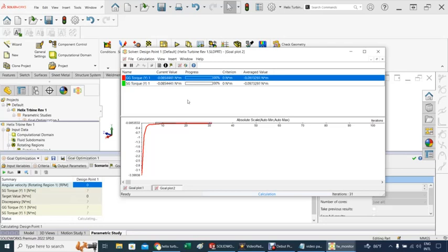Remember, we are doing this now totally automated because basically we know that at 0 we got maximum torque, which is a negative value. Then as we allow the spinner or the turbine to rotate at maximum speed, then we have to apply torque, and that's a positive value. So between the positive and the negative, we know that there's a sweet spot in which the turbine will sort of free rotate at a given RPM in which you are not adding energy or extracting energy.